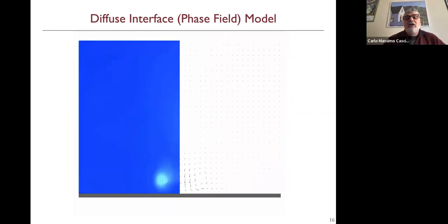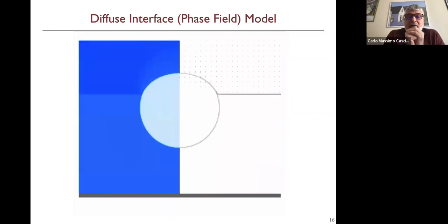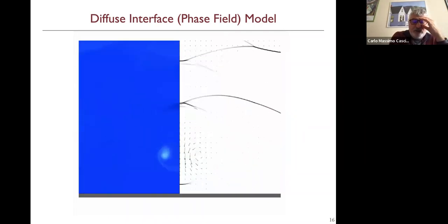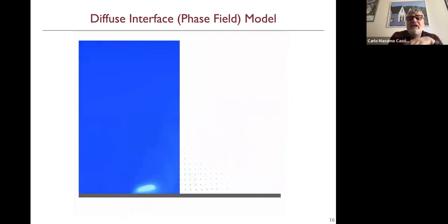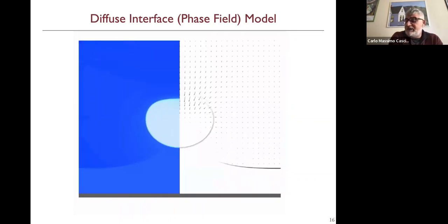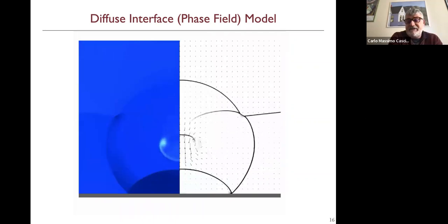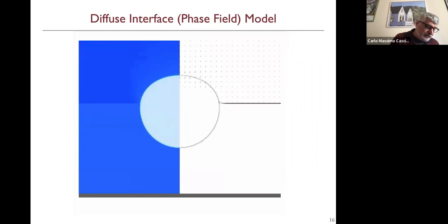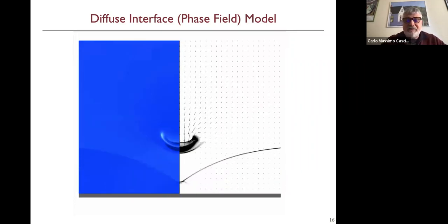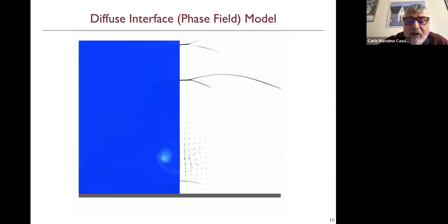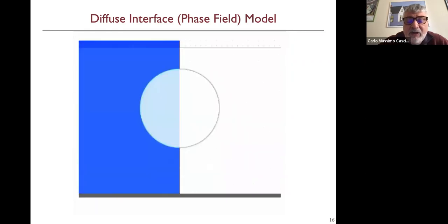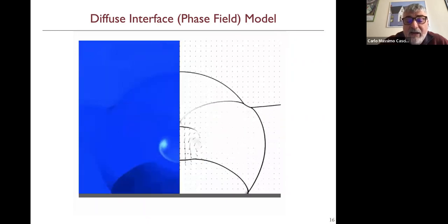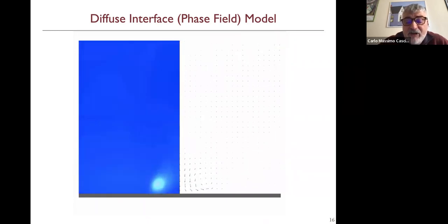In the meanwhile, due to the bubble collapse, a complicated system of pressure waves is launched in the liquid. So you see that this strongly nonlinear system, endowed with phase transition, the possibility to transition from supercritical to subcritical state and vice versa in the vapor, and so on, is able to describe a rather complex process that takes place when a bubble collapses near a solid wall.